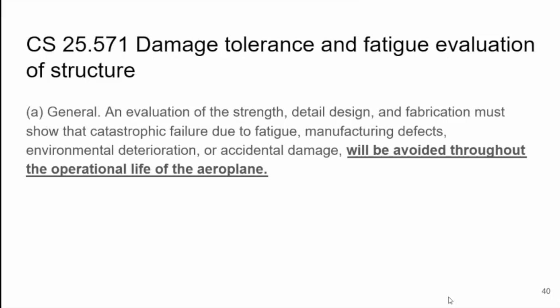This is a bit tricky because we do not have a standard material SN curve, stress and cycle curve, and this is something that during the development of the materials you also have to determine. As you develop the material properties, this is one of the areas you need to determine. That's why, on the 777, I was told it took two years to get the material system.